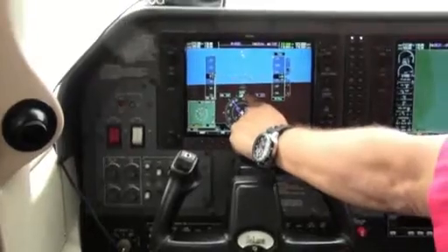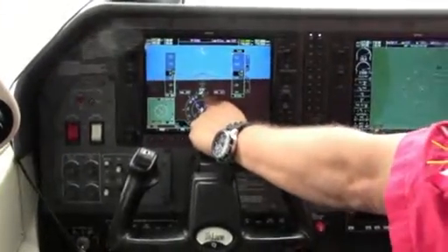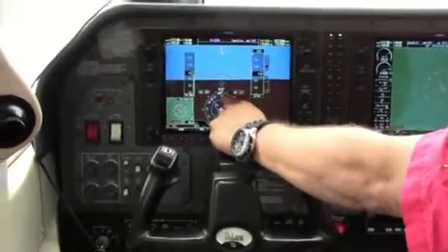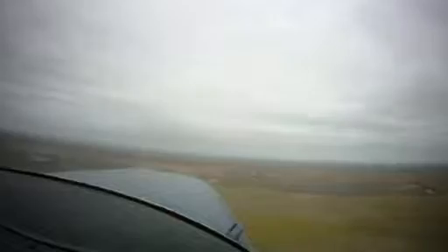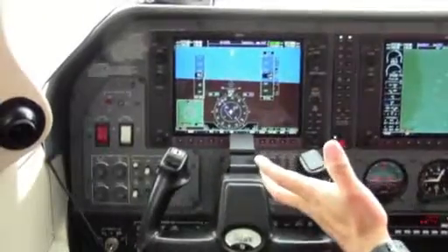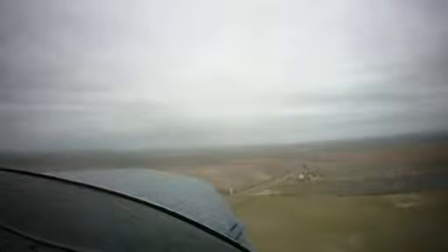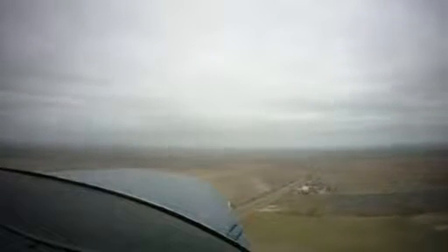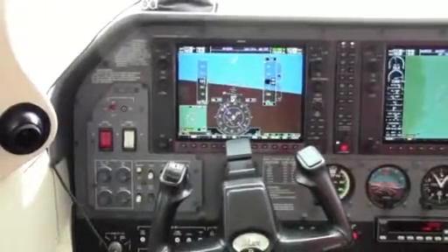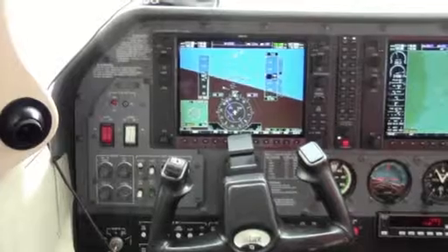I'm going to use this little mark, the blue bug, as reference. That's my runway right there. So I'm going to go about 15 degrees right, to make sure that I have the center of the runway. Now, how much do we need to curve into the wind? It will depend. It's just give and take. Airport traffic November 65328, entering left crosswind runway 32, full stop, airport.